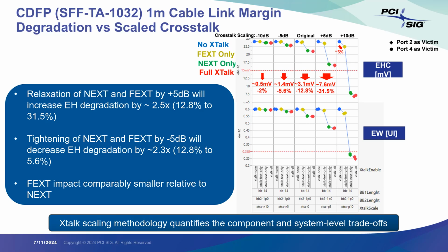So the main thing to look at here is that in any of those graphs, you will see there are certain points where, if you increase the crosstalk by more than 5 dB or 10 dB, you fall off a cliff. So we try to find those transition points and then decide that degrading further will be pretty disastrous.